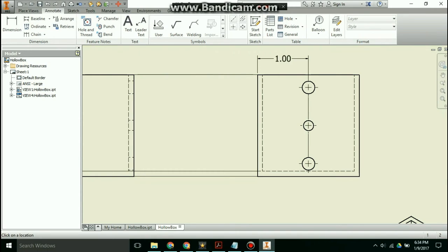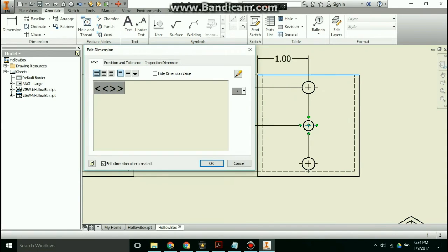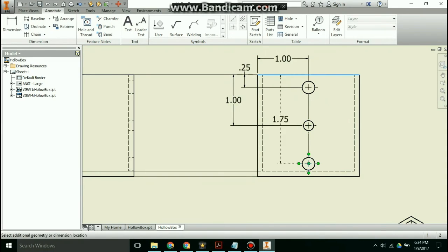Now it's much clearer. We also want to make sure the reader can see the side length. This is going to be 0.25, 1.0, and 1.75. Although you may want to do a dimension like this, where it's 0.25 here, that will get confusing and is ill-advised, because you already have a 0.25 here. It's better to start from one base and go all the way through.